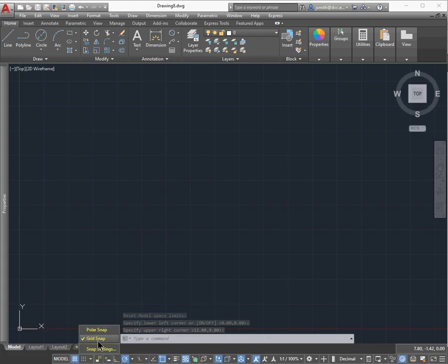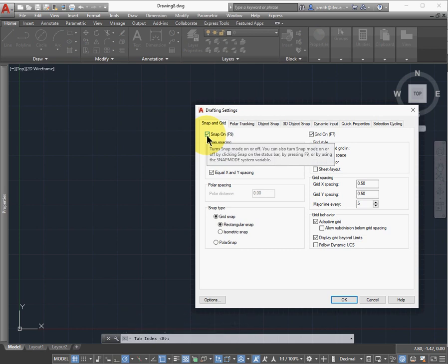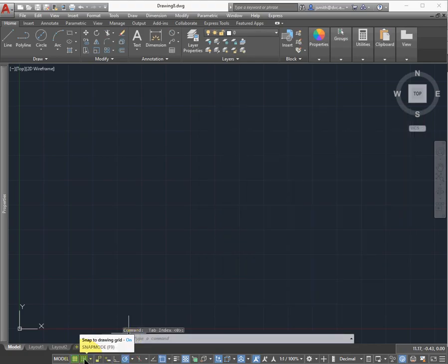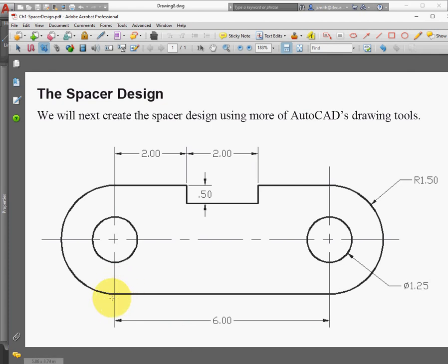Okay, so then you can look at your settings. If you click on the snap settings, there's a couple things that I tend to do. The textbook wants you to use the snap on. I find this very difficult, but increments of ½ inch can be helpful. And then I always have the polar tracking. You're going to want to make sure that you have these three selected: the center, the midpoint, and the end point. If you don't have those, it's not going to work for you for this project. This is just some of the formalities that the textbook's asking you to do, so make sure that you follow them.